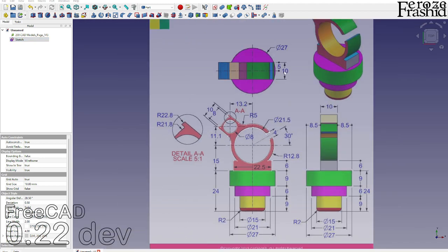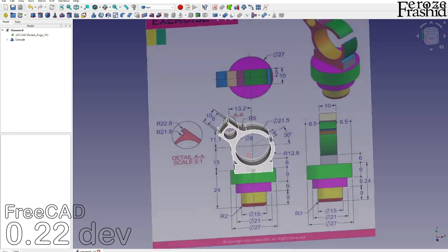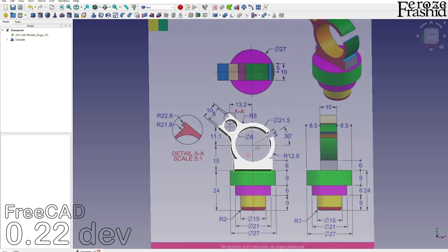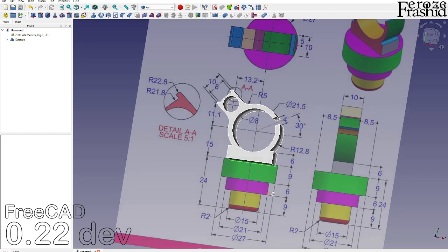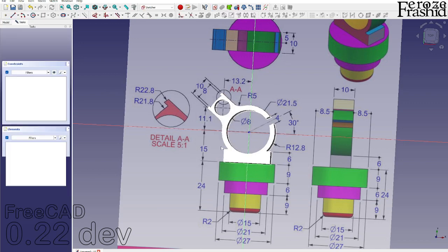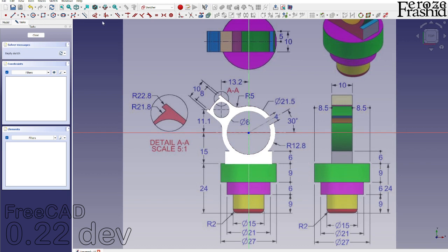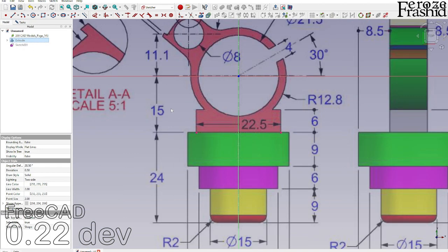And let's go ahead and extrude that for 10 millimeter, but in a symmetric fashion. So symmetric, apply, close there. So there is our ring. And then we will do this lower part as a revolve. So that will be another sketch on the XY plane, and probably take this line as our reference. So that's GX on the keyboard, the external geometry, and then hide it. So we have the GX.